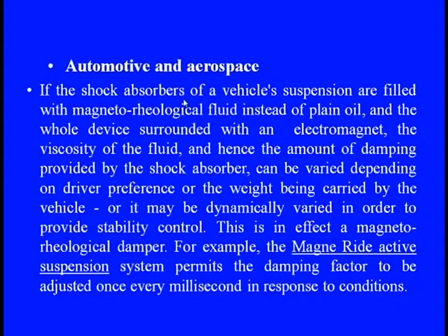In automotive and aerospace, if the shock absorbers of a vehicle suspension are filled with this MR fluid instead of plain oil, and the whole device is surrounded with an electromagnet, the viscosity of the fluid can be enhanced, and hence the amount of damping provided by the shock absorber can be varied depending on the driver's performance or the weight being carried by the vehicle.